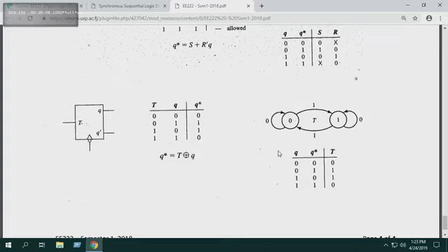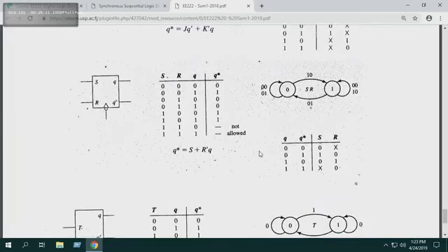Okay, all happy? Okay, now guys, just to let you know, in class I've taken you right in the beginning, week 8 or week 9 somewhere. I took you through all the basics of SR. I showed you, oh, this is how we build the SR latch. Then if you put a clock cycle, some NAND gates to make the clock button, this is the SR flip-flop. From the SR flip-flop, we got the truth table for the SR flip-flop. Then we got the characteristic table, then we extracted the formula. Then from the formula and the characteristic table, we found the excitation table. Yeah? An excitation table, and this is the same thing.